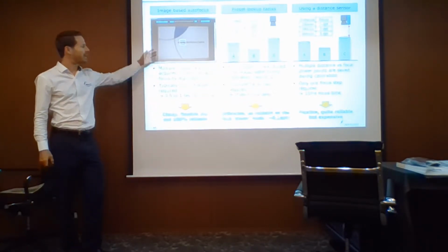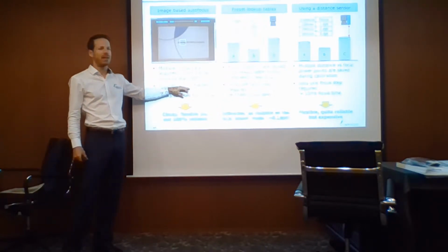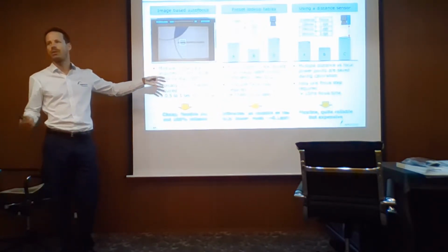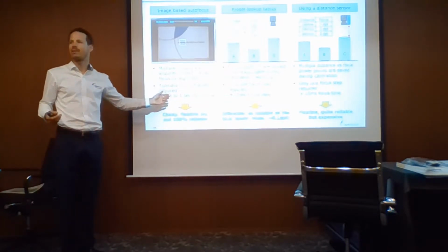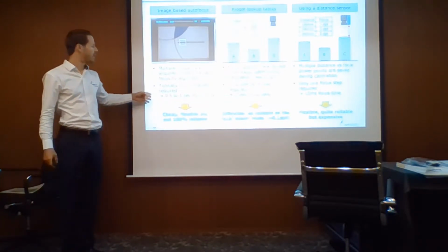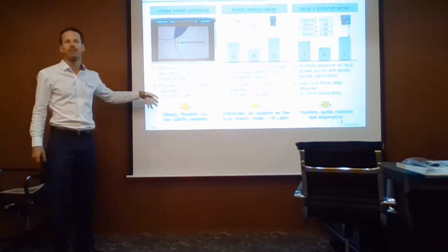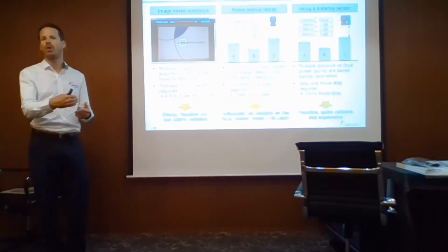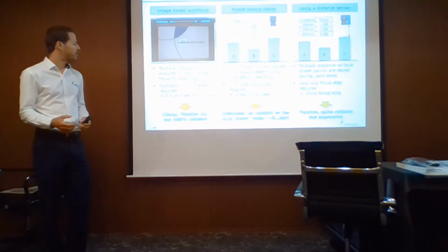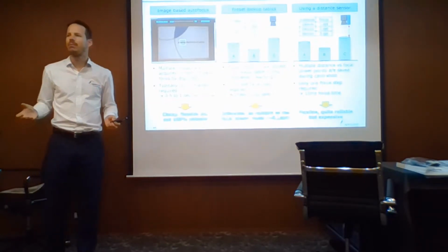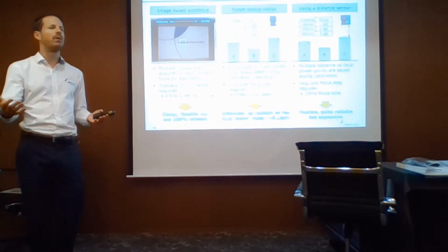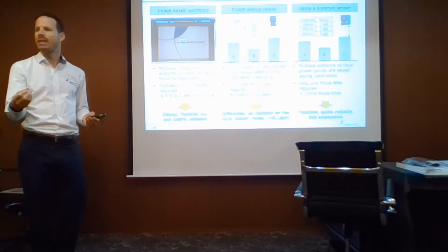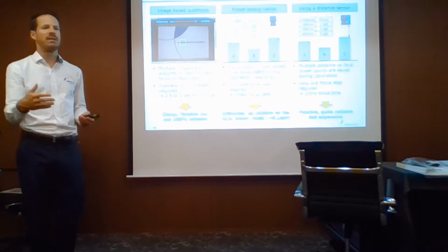Now, with our lens, we can do that within about 20 milliseconds each. So in theory, after 200 or 300 milliseconds, you can do an autofocus. In practice, it's a little bit more, but definitely faster than 1 second. But of course, it's not completely reliable, because if you focus on a white piece of paper, chances are good you don't see any contrast, and then you see nothing.